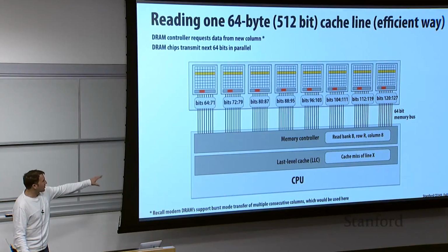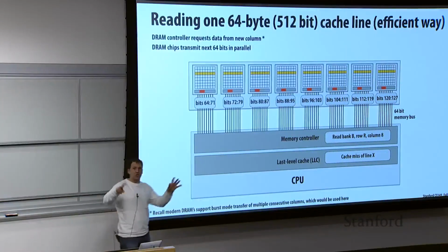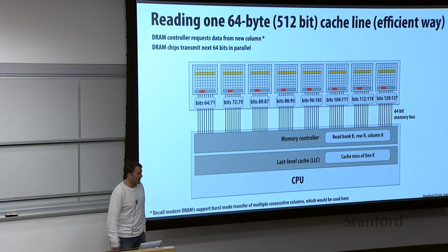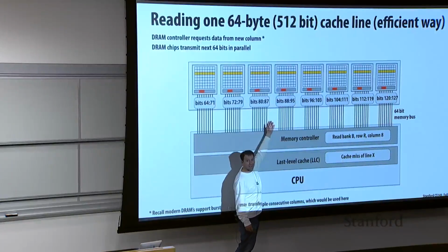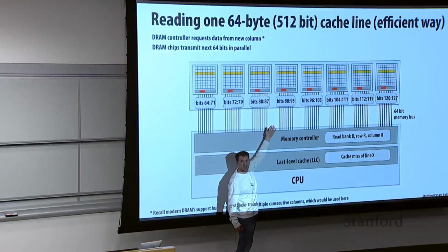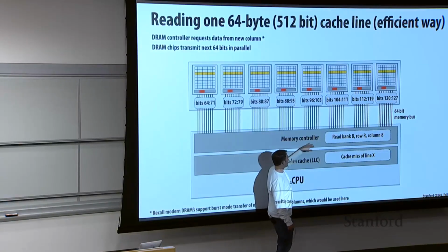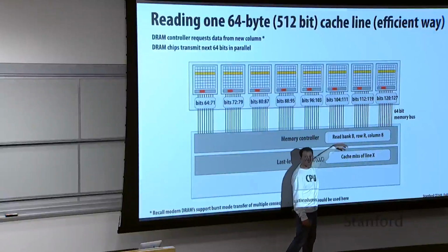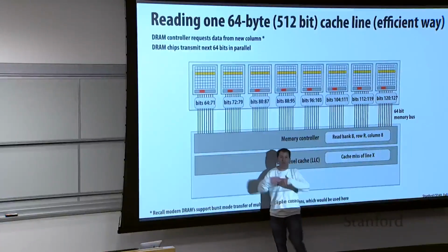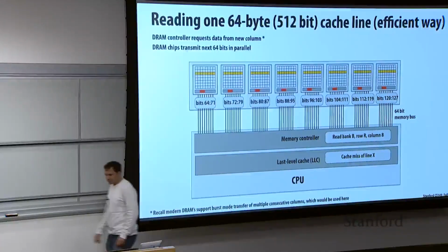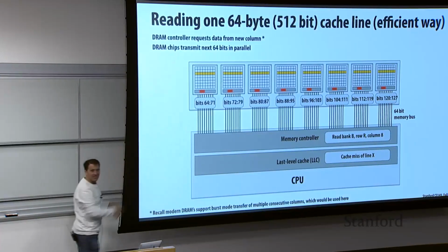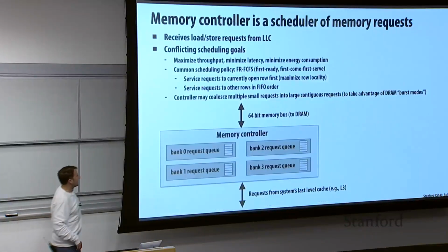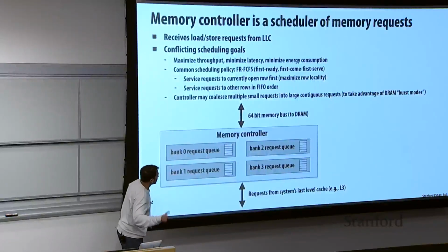But yeah, okay. So this is your basic memory unit. And then sometimes you'll hear things like a dual channel memory system. You can think about this as one channel between the memory controller and a memory module, a DIMM. Notice that one channel has one command per clock, and the same command is given to everybody. A dual channel memory system is just to take this and make another one.